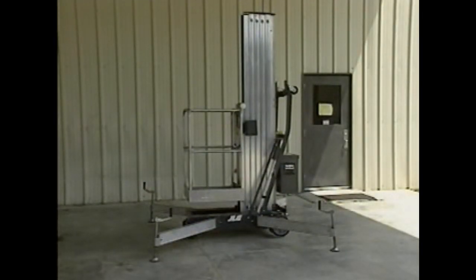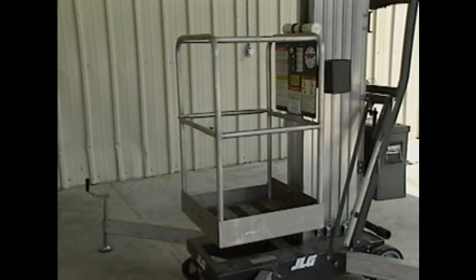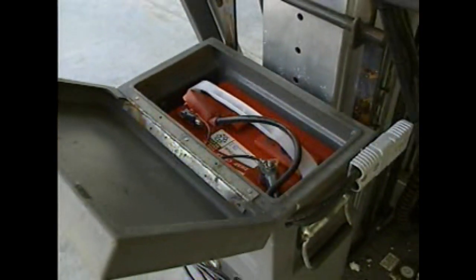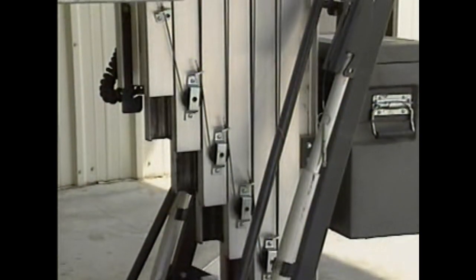Here's the hydraulic scaffold that we'll use for our discussion. Among the major components of this scaffold are a floor or platform for a worker to stand on, and a cage to prevent the worker from falling off the platform. The work platform is attached to an upright or mast that's divided into different sections so that it can basically telescope up and down. A battery supplies power to an electric motor, which drives the hydraulic system and enables an operator to raise and lower the work platform.